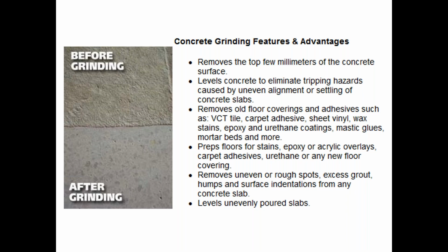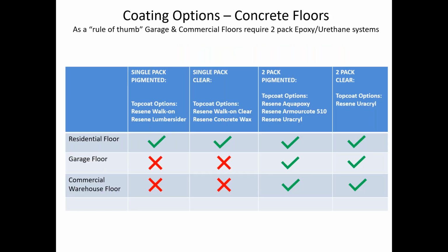There's just huge advantages. The other thing too with diamond grinding or floor grinding or concrete grinding, whatever you want to call it, is there probably isn't a town in New Zealand that doesn't have a concrete grinder available to come and do this job for you. So they are everywhere, and they can do different grades of grinding too. So if you're just going to put flooring on top of it, you just do an average grind. It doesn't matter if there are grinding marks. So you need to talk to the grinders and say what sort of finish you want, whether you don't mind the odd swirl in it or you want a high level of grind, right? So you can have a wee chat to them about that.